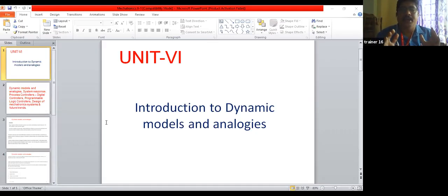So in this, if the output is not our desired output, what do we have to do to get our required output? With the help of sensors and transducers, we have to send some feedback element again to the input, right? And this input, with the help of the sensors and transducers you studied in Unit 1, and the next step, Unit 2, the analog signal conditioning, we have to use various amplifiers and filters to overcome that error.